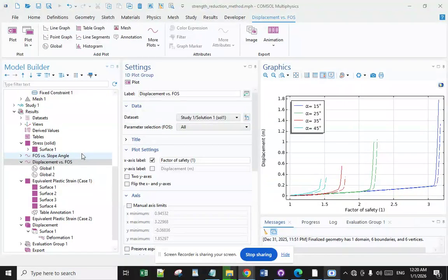Process control must be in place, and effective quality management systems such as total quality management need to keep actual production within the desired tolerance. A process capability index is used to indicate the relationship between the tolerance and actual measured production.